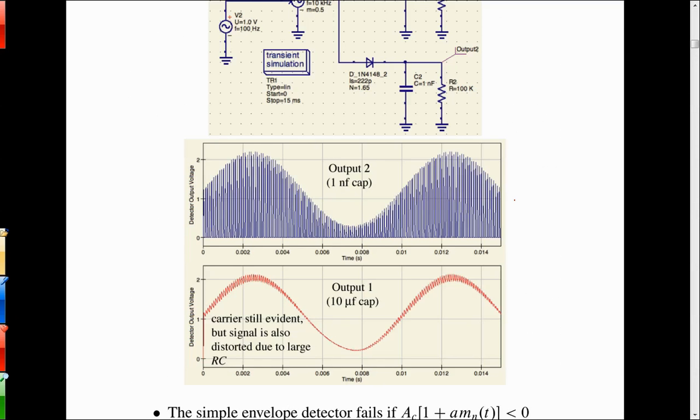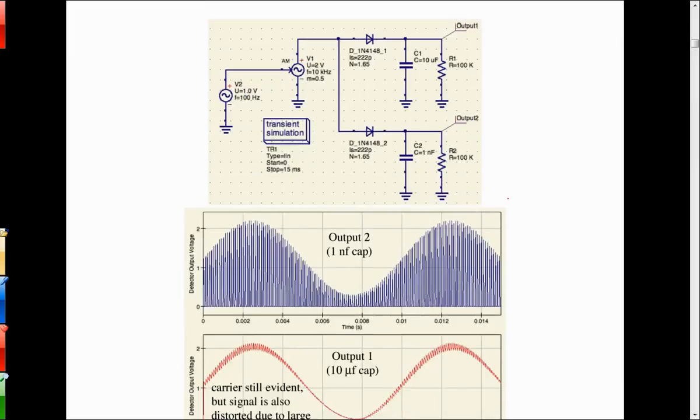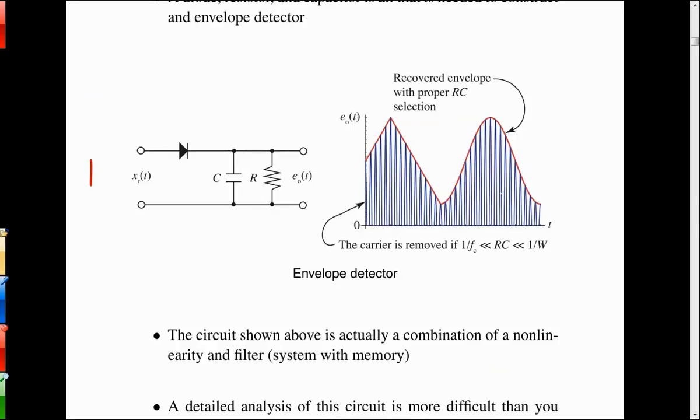Way back up here to these pictures, to make sure that this gets driven properly, because if the signal was to get too weak into this envelope detector, then the diode wouldn't necessarily turn on, or you'd have issues with this circuit. Of course, it's done differently in modern implementations. This is kind of like the baseline traditional implementation with a rectifier diode. But that's part of the receiver, and that's done on the RF signal, or actually on the IF signal. We haven't talked about intermediate frequencies yet, but we're getting closer to that. So automatic gain control devices are there.